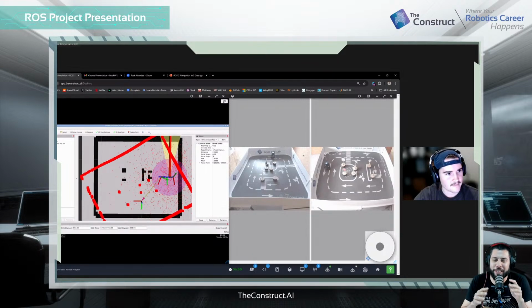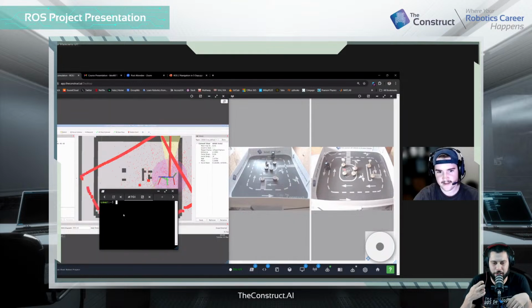That's basically because of the remote nature of this. RViz for some reason has trouble displaying the cost maps, but it doesn't mean they're not there. Otherwise your application wouldn't work, because it would be like, "Where are my cost maps?" It's just RViz's inability to show them. So yes, it adds that little bit of a complication.